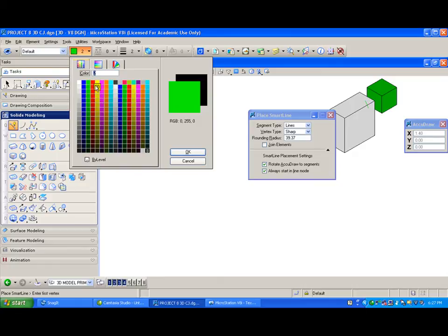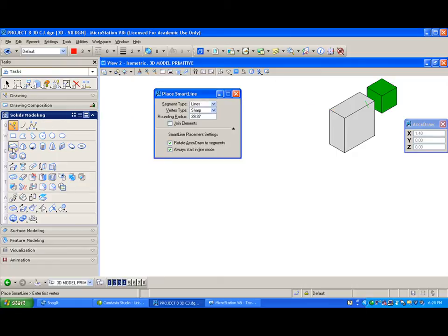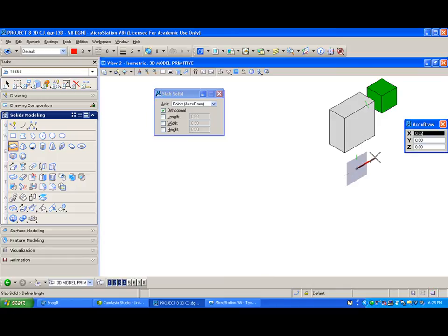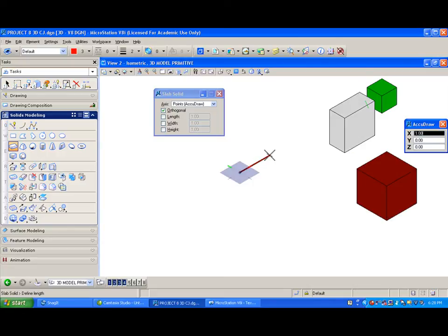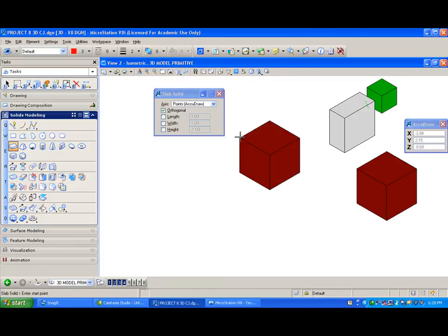Now let's imagine we want to draw another box. We're going to left click here, and hit rotate top, T, and we'll say 1 by 1 by 1. Now after I set the first distance, 1, it automatically stays in the top and allows me to do the second distance. And then you'll notice that the compass automatically flips up. It's no longer a top view, it automatically flips to a side or a front view and allows me to create these boxes. So we can draw everything in the isometric view.